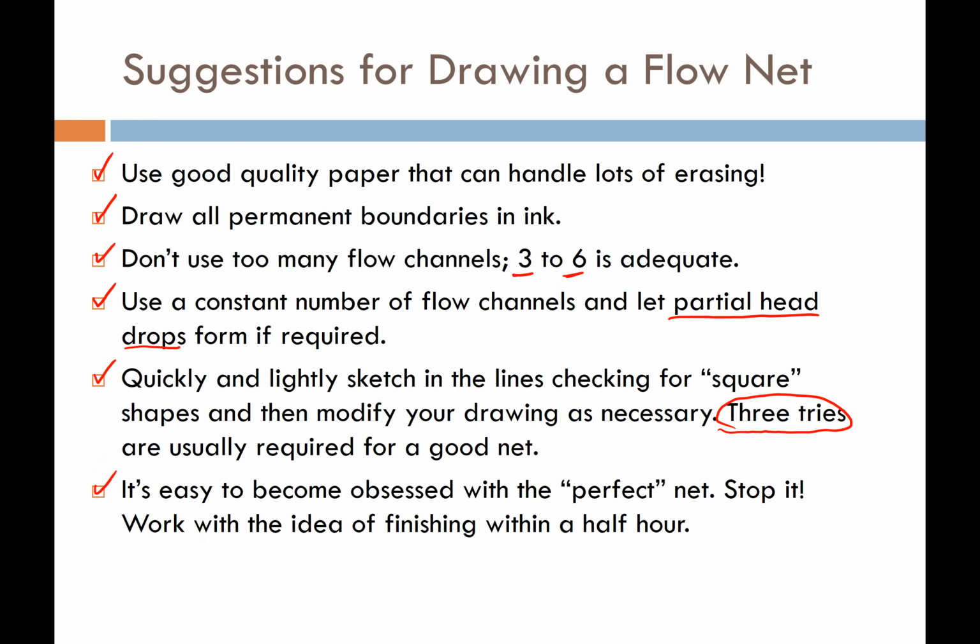And that leads to, of course, my last point. It's easy to become obsessed trying to draw the perfect flow net. Just stop it. Don't worry about that. I generally say, work with the idea that you're going to spend half an hour drawing a flow net at the max. And after half an hour, it's probably going to be good enough to get a reasonable answer.